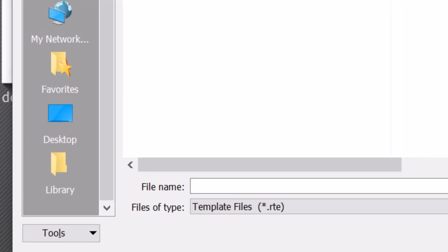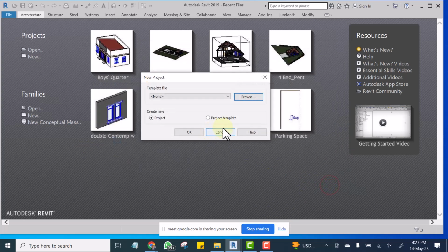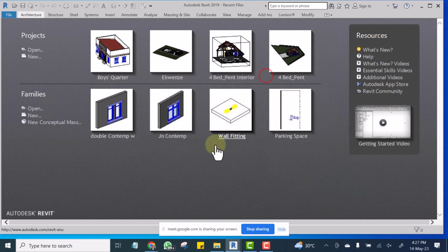you can see this particular Revit doesn't have some of those default Revit templates. This particular installation doesn't have those default Revit templates. In case you happen to have a Revit installation like that, what I will recommend is to use an existing project.